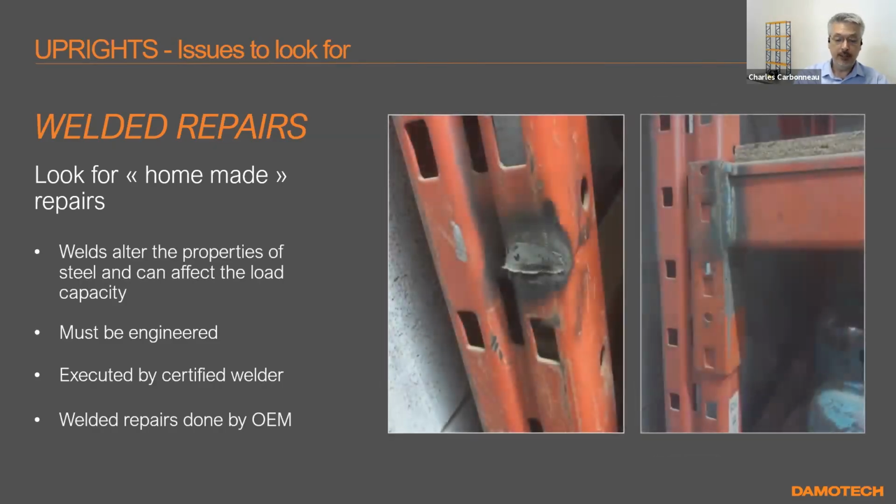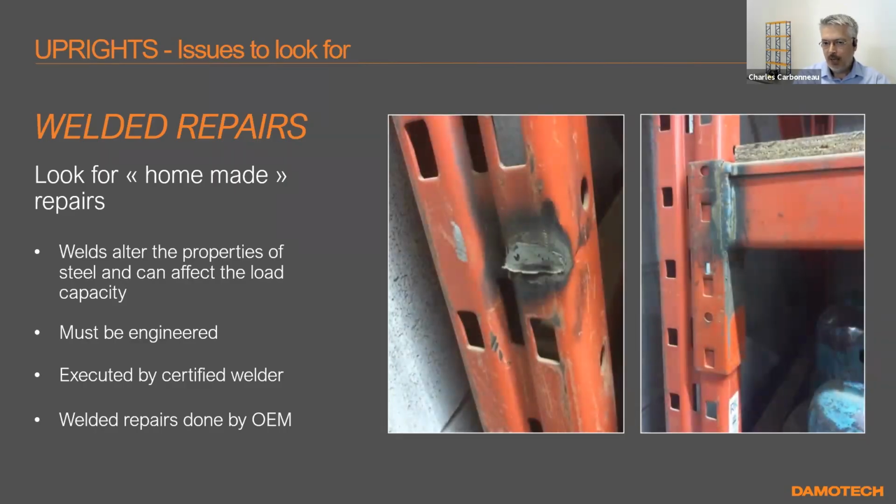And so for an engineer, it's really, really hard to decide, is this good or not? Especially when you look at these pictures where you see they did not even prepare the surface. So they welded right on top of paint, and that will contaminate the weld, right? So the adherence between the metals that you're trying to accomplish, it's a mix of chemicals, and there's paint in there that's been mixed. And so to me, the picture on the right looks really good, but you ask an engineer to take responsibility on this and say, yes, you're fine, you can operate, and I'm putting my name on it, go ahead. Well, it's worrisome for the engineers.